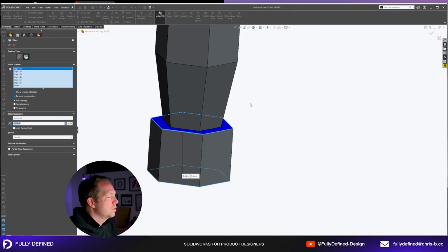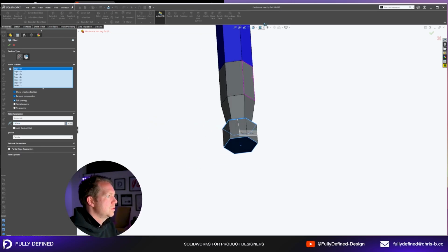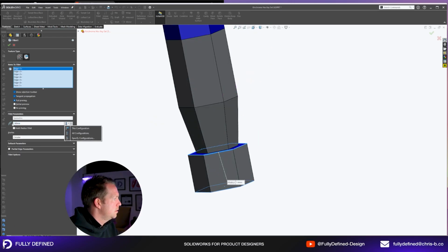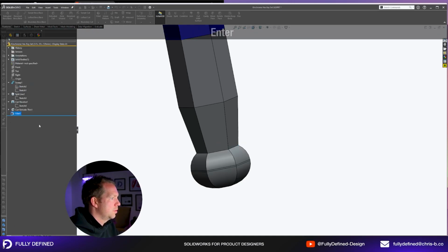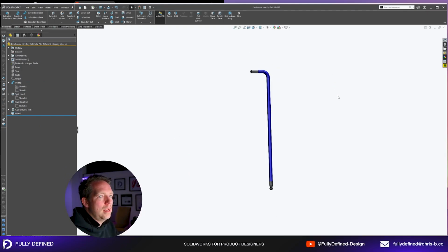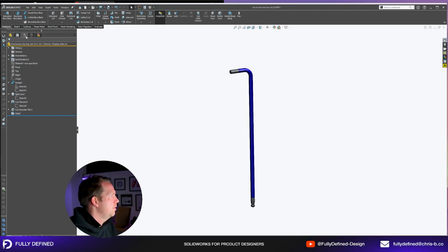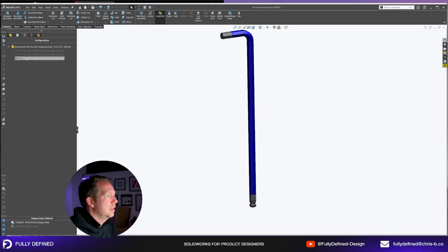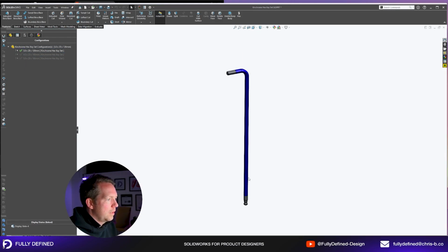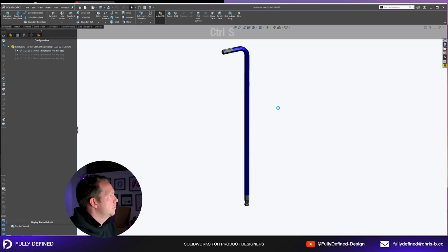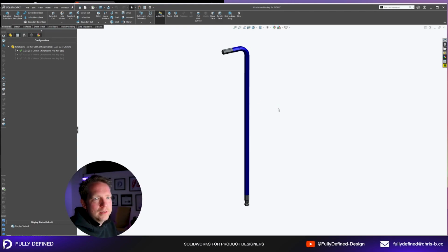So what we're going to do is we're also going to reduce the size of the fillet now that the length has reduced here. Okay, so we're going to link that diameter or the radius of that fillet, this configuration. We're going to reduce it until it works. 1.2, it's okay. And we expand out, and what we should start to see now is 3 clear sizes using the same features, okay, but with the differences between each. So there you go. I think I just want to show you how this looks then in an assembly.